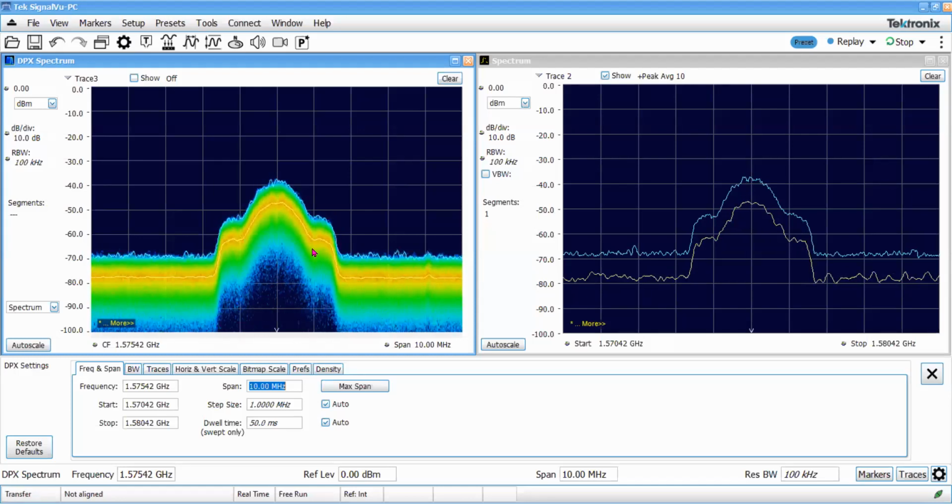So the receiver design is very complex and needs different filtering techniques. But GPS L1 C/A has a very small bandwidth, yet is very nicely designed. So the receiver design is very simple, and that's one of the reasons why GPS L1 receiver chipsets are very cheap as well: the design is simple, and that means lower cost.